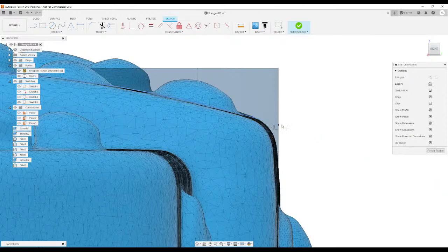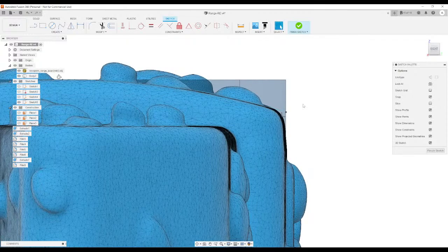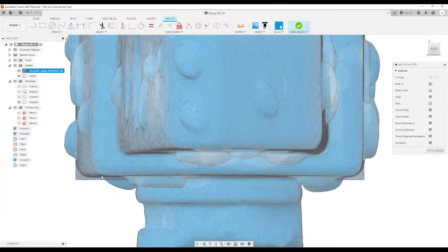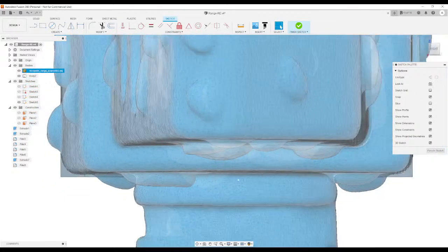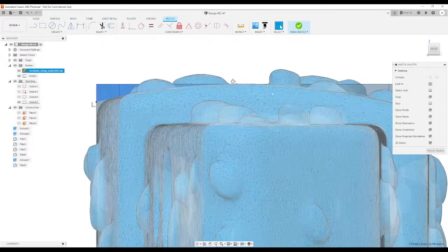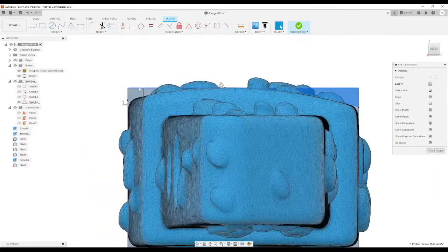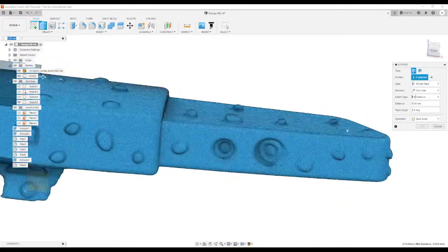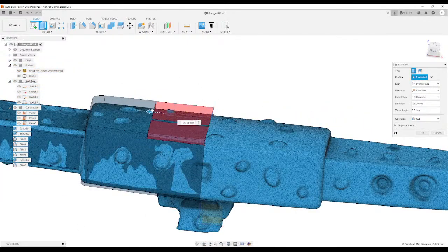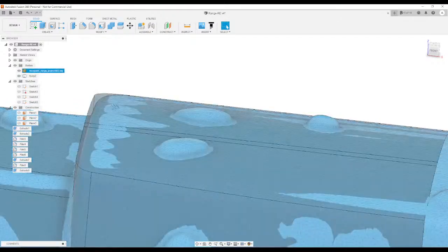If we do this, it will go into the infinity, but we don't want it. What about the bottom? Is the bottom straight? I think it is. Yeah, it is pretty much a straight line. We will have just moved the bottom face a bit. Okay, so let's select these two faces, finish sketch, select one face, select the other with the shift key, extrude, E key, and let's run this until it ends. Basically something like this.